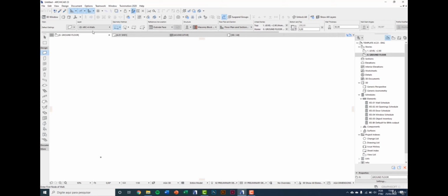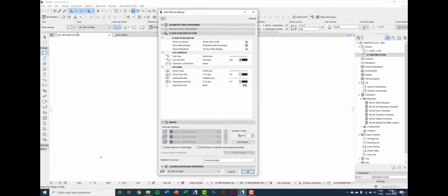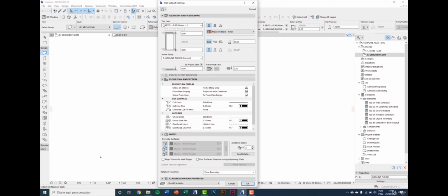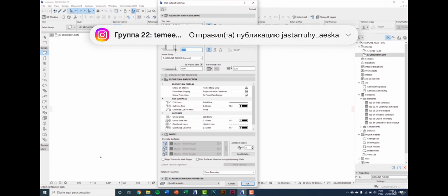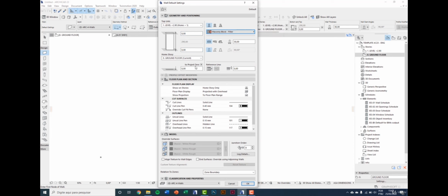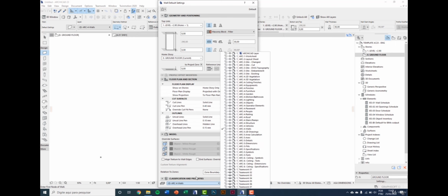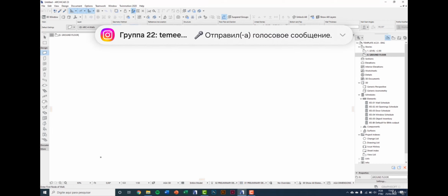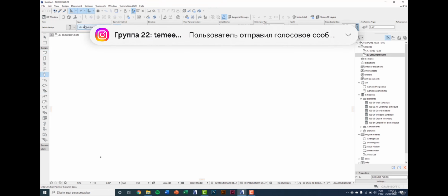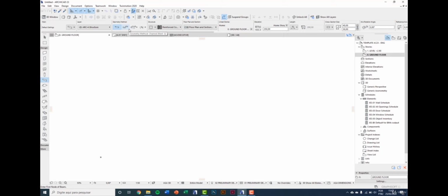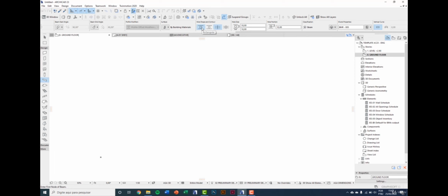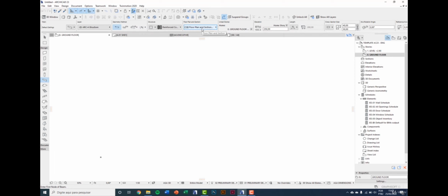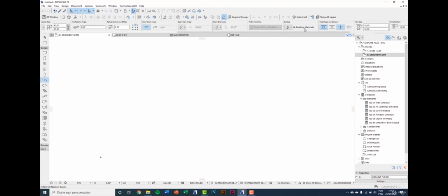And every tool has this button. It is the Settings dialog, where you can enter and define many settings about the tool, like the levels, wall height, building materials, 2D representation, surfaces, and layers. Then for each element, the Info Box changes its information. If I change to column, you can see beam, and rolling the mouse scroll over the bar, you can access more options. So you can roll the scroll of the mouse and access more options in this Info Box.